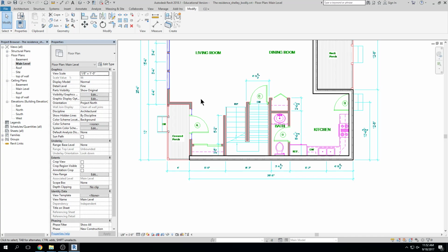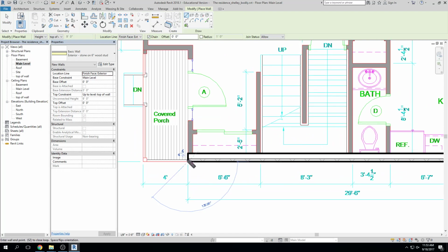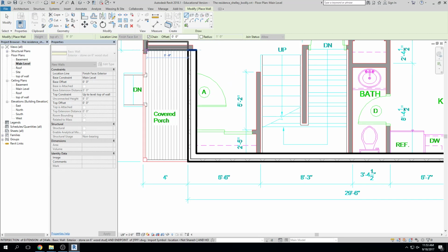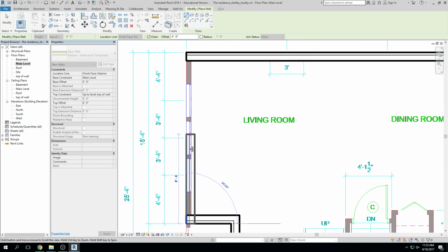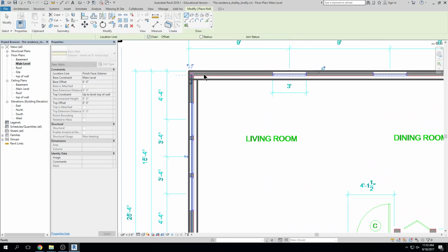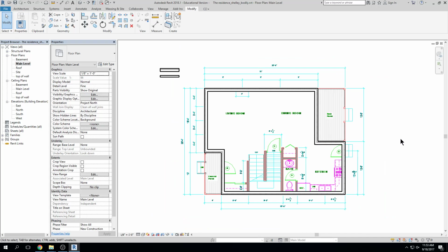Okay, just going to continue on, grab my wall, create similar, right? That way when I use create similar, I know I'm getting the exact same wall type. I'm not accidentally picking something else, and I just keep going, and these walls will join and clean up the end. There's my little house, right?